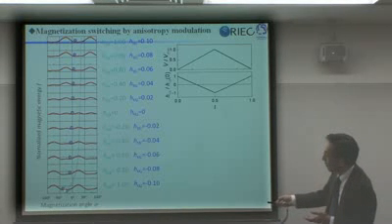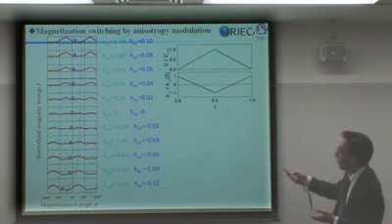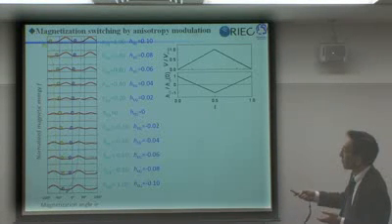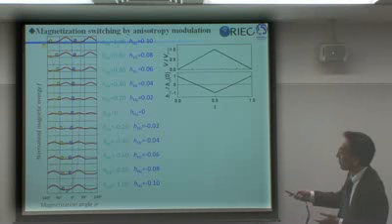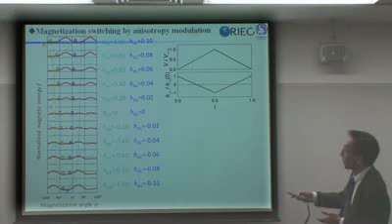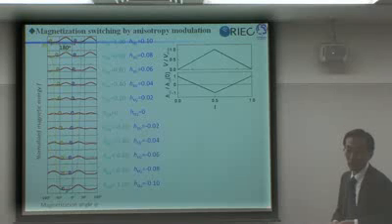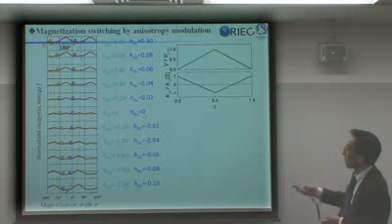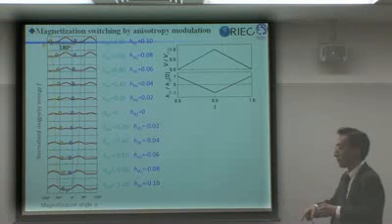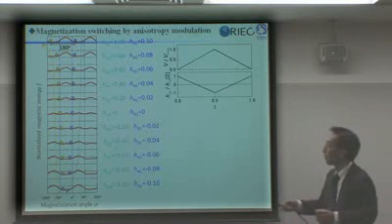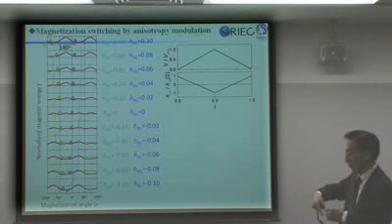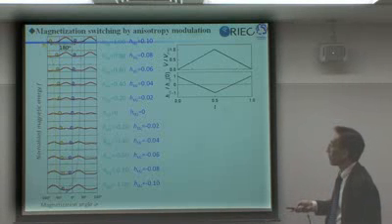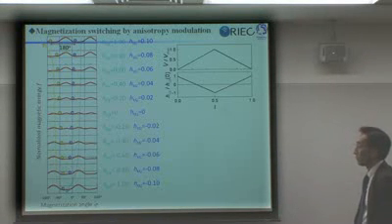And if you start from here and if you go back, actually it will not go back to its original position, but the trace or the trajectory is different, and you can have a 180 degree switch. So basically what you're doing here is that you're using the anisotropy landscape to form a ratchet motion. So if the product of the two is negative, then it goes the other way around. So if we can achieve this second term, we should be able to do 180 degree switch.